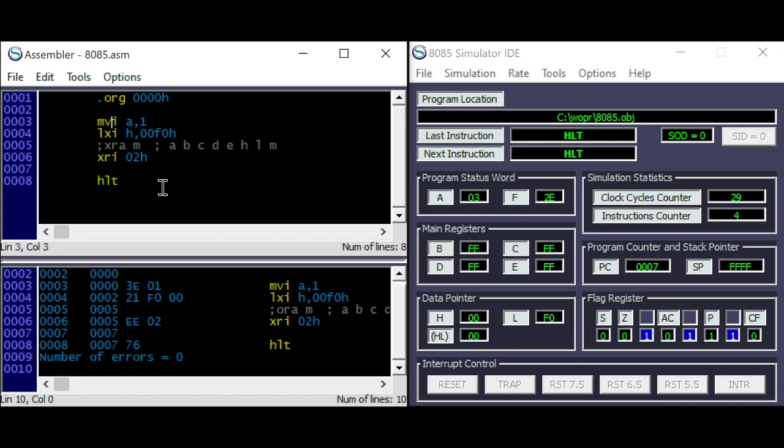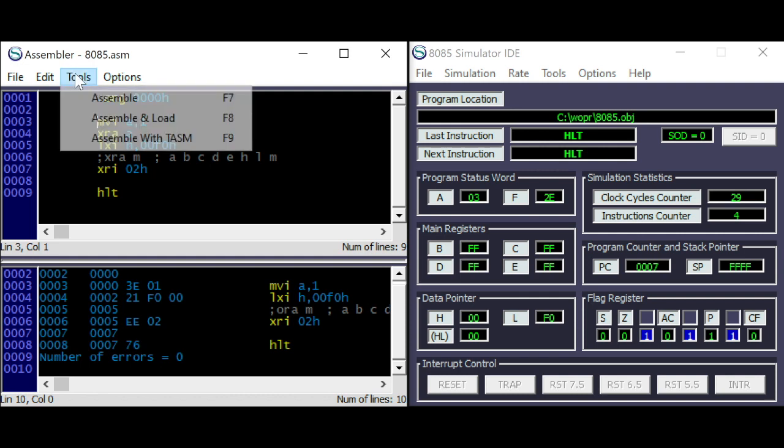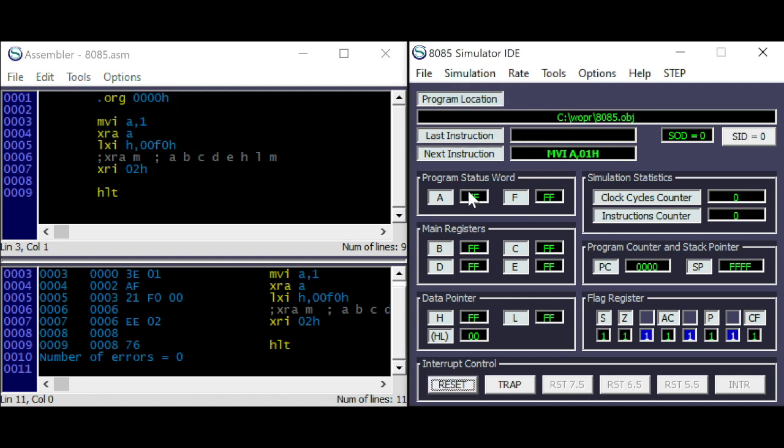And one thing we will often see is this command, Exclusive-or with the accumulator. So what will happen here? A is 1, Exclusive-or with itself, so there's no difference. The accumulator will be 0. Zero flag is 1, parity is 1. And this one is often used to clear the accumulator.